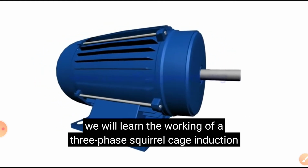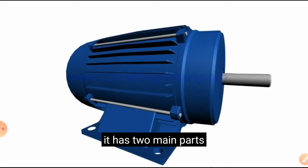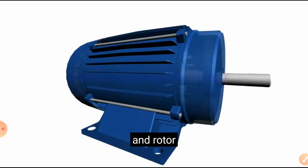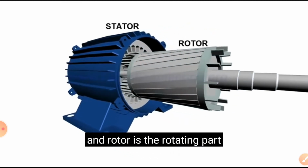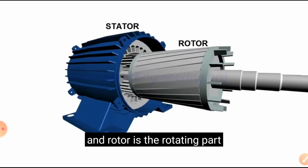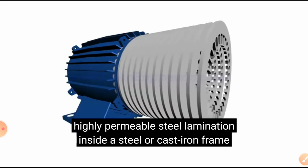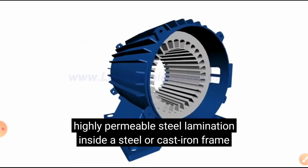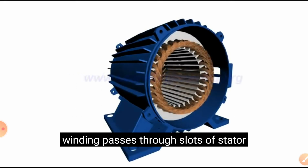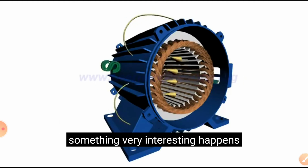The motor's outside body and terminals protect against mechanical damage to the internal parts, mainly the stator and rotor. The stator has laminations of 0.35 mm to 0.5 mm, made of silicon-containing material, and the stator has a 3-phase winding distributed 120 degrees apart.